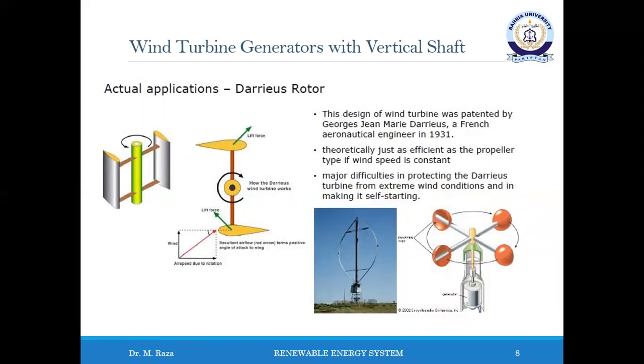Because the wings are symmetrical and the rigging angle is zero, the rotor spins at a rate unrelated to the wind speed, and usually many times faster. The energy arising from the torque and speed may be extracted and converted into useful power by using an electrical generator.